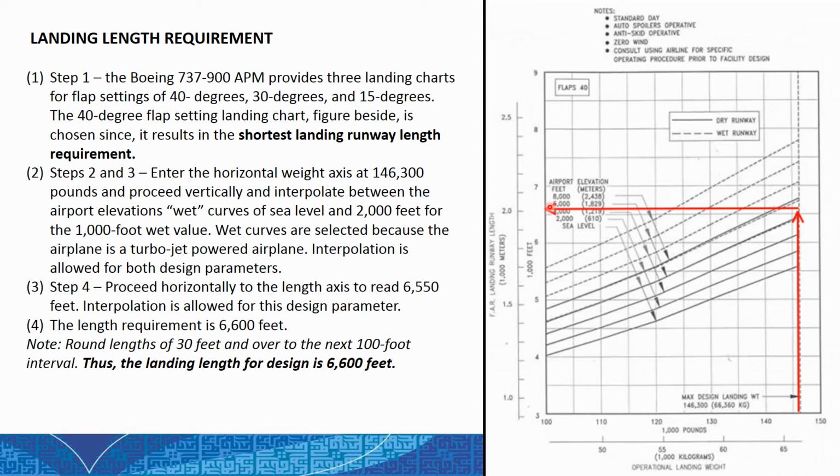So the length requirement is 6,600 feet. Why? Because we will round up to the next 100 foot interval. So 6,550 feet will become 6,600 feet. So for the landing length requirement, we get this.